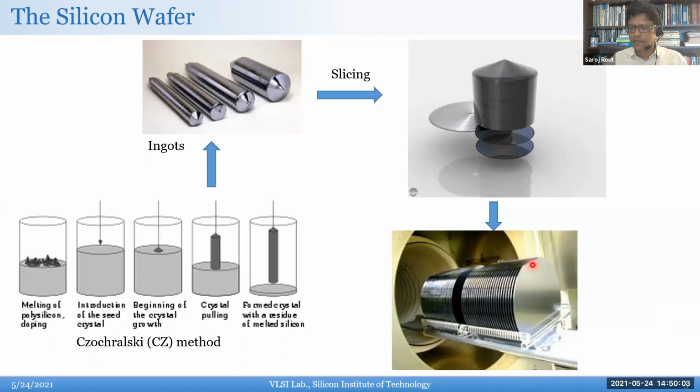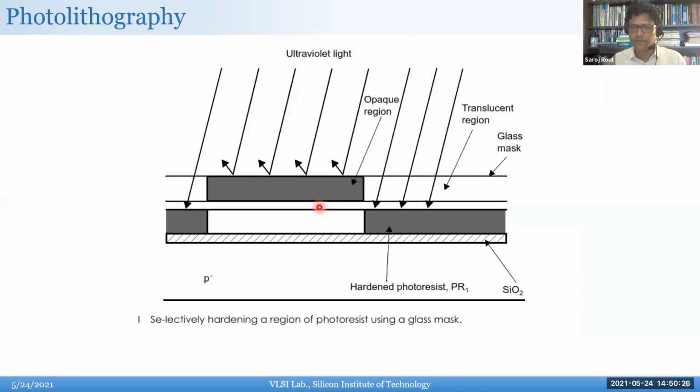So I think having this tab keeps them aligned when they go to the next step, because when they take the mask, it has to perfectly align with the previous one. If it is not, then everything is a short or open. That's the challenge, and that's what I was telling you about: why the self-aligned gate is probably what made Moore's law possible.